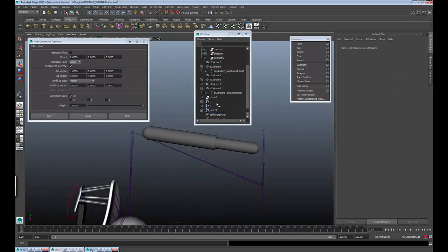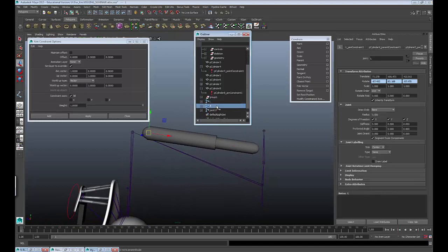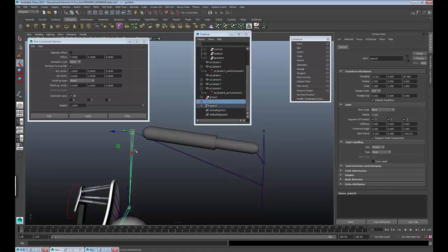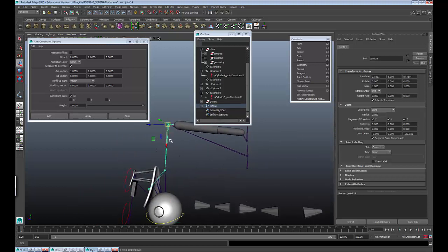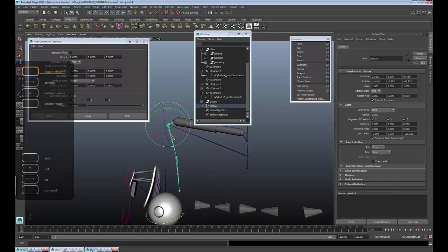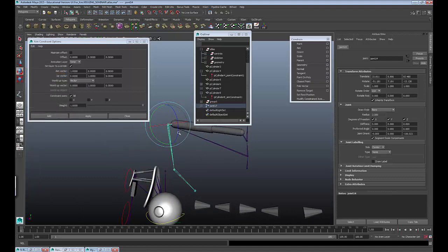And then what we're going to do is connect our left and right joints. So the right one goes to the torso side. So I'm just going to parent that. And the left one goes to whatever arm component or leg component or knee it might be. Cool. So when I'm moving my arm around, this is going to cause that to move, right? It's going to be like a little kind of actuator, causing that to move around.